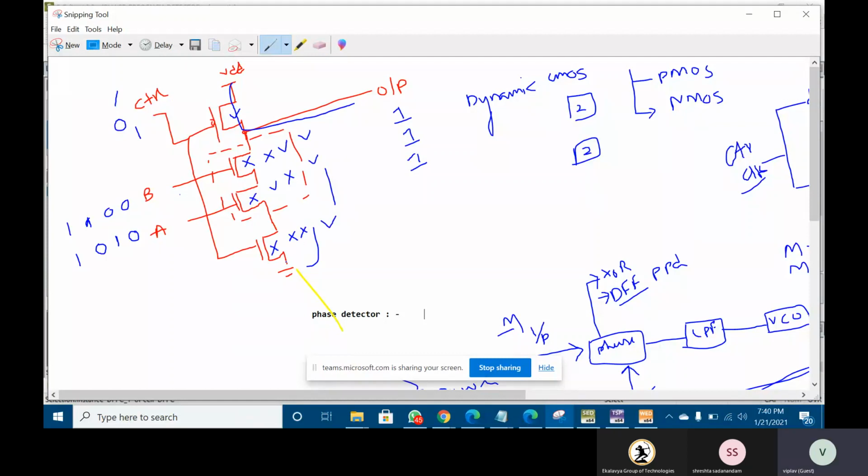All the NMOS transistors get on, so the ground supply will go through the output. So now we will get the output, that is 0. 1, 1, 0, which is nothing but the NAND logic. So we are getting the NAND logic with the help of CMOS.